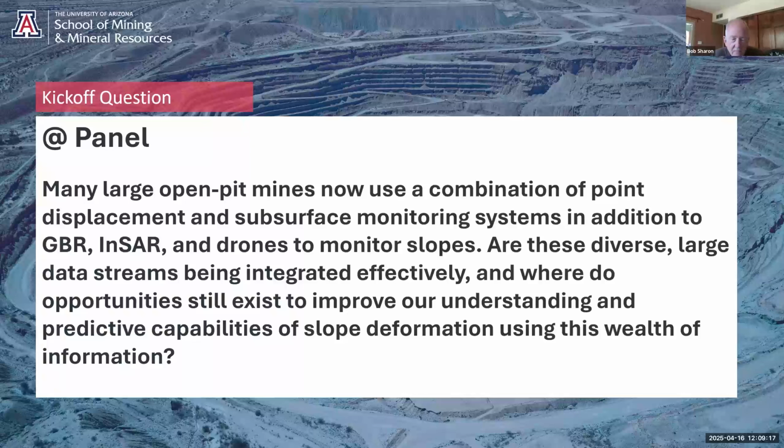I've been to many operations who do this very well. They'll take point measurements, for example, and combine them with other data for interpretive context. So if you're monitoring slopes with prisms, for instance, a lot of operations nowadays are increasing utilization of ground-based radar systems, InSAR, and other types of instruments to monitor pore pressure, like vibrating wire piezometers and so forth.